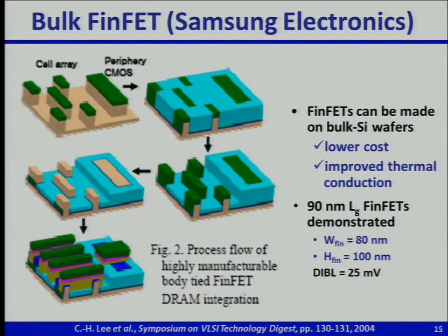So for analog circuit applications where you want to fine-tune the ratio of transistor strengths and so on, it's not that trivial. So actually, a planar bulk device would be just fine for analog, because in an analog circuit, you never turn off the transistor, right? You just keep it on and you just modulate how strongly it's on.